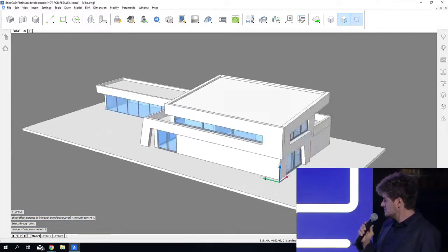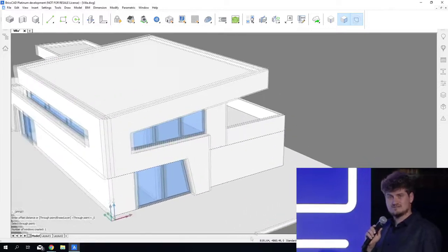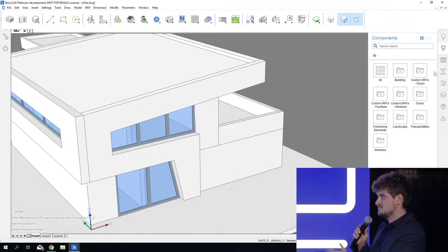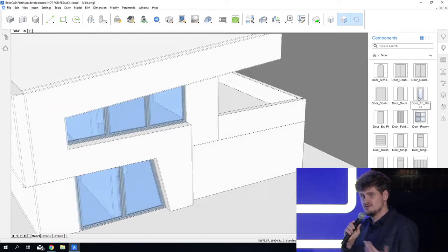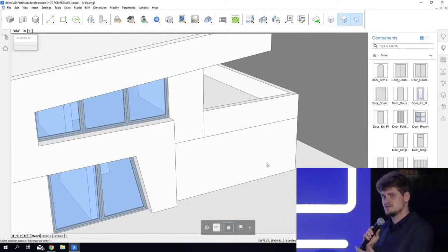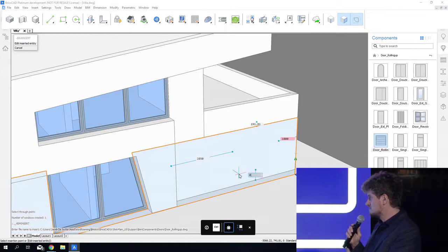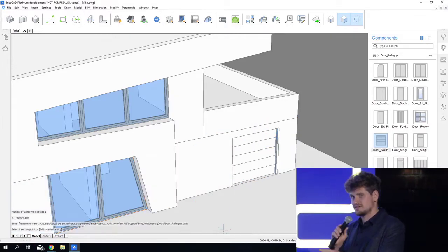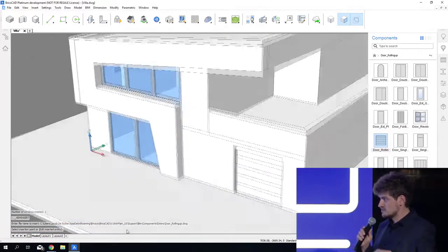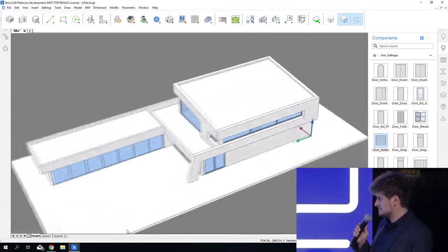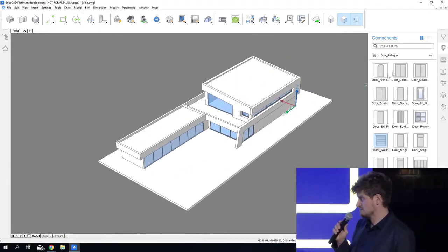Two years ago, we actually started with first classifying solids, so that if you have just geometry there, you can know which ones are the walls, which ones are the slabs, which ones are the columns. Last year, we added to the BIMify process that we could also detect where the buildings are, where the stories are. And this year, BIMify has been extended a lot more even.